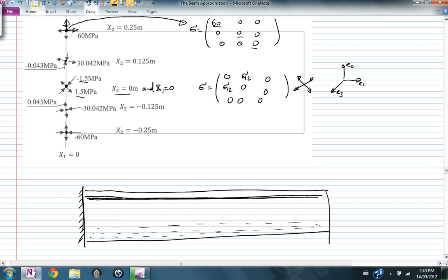When you look at the middle of the beam, you'll find that the principal directions of the stresses have tension in this direction and compression in the other direction. Tension in this direction, you end up putting some steel bars for shear. Some other people use something called shear studs. So they put shear studs in this direction just to take this type of tension due to the existence of the shear stresses at this location. But the reason why you put those bars is to take the tension, or they're usually aligned with the principal stress directions that are tension.